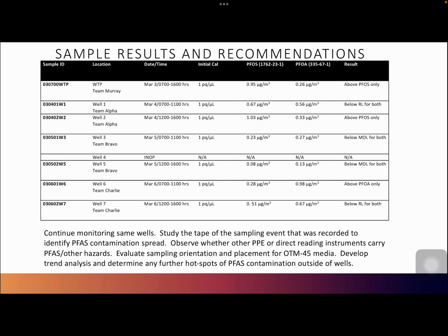Here were the sample results that I had for the event. The water treatment plant was above the limit for PFAS, as well as well 2, and well 6 I had above for PFOA only, with each monitor going for about 4 hours. And well 4 was not used because, as I mentioned, it was inoperable.